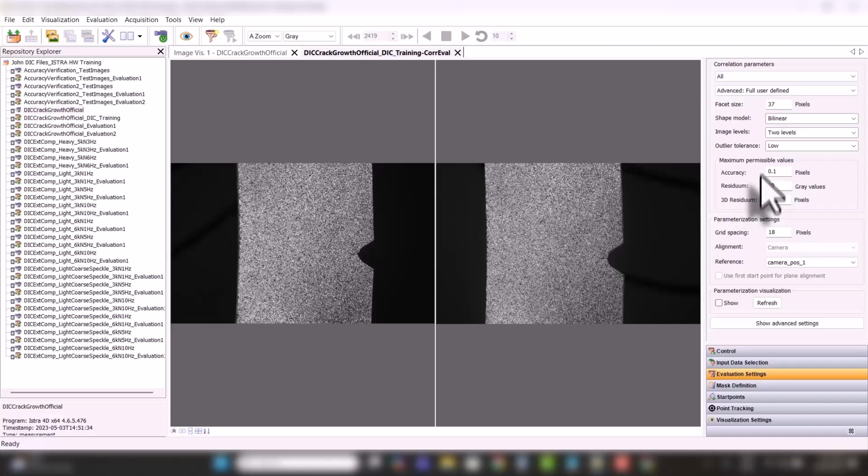And again, you might be thinking, well, I don't want to bump this up too much and get correlated results that are incorrect. Well, no, you'll see that they're incorrect. You'll probe the values and you'll see that you're looking at just pure noise or close to pure noise. And so it will tell you. But yes, in general, if you bump these values up and the correlation then succeeds when previously it was failing, the values you get are going to, in general, have higher precisions. But when you append this data onto your existing field of data, those precisions will be reported with the values. So you'll see the quality of the data.